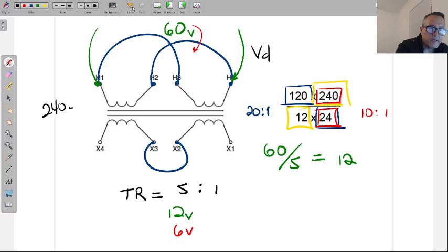One of the ways you can compensate for that is a step-up transformer somewhere along a long distance run. Now, it's not as common for us to run into a situation like that. For example, the power company runs into that a lot as they run power lines very far. So they use a lot of step-up transformers, but we just simply don't have a lot of uses for them.